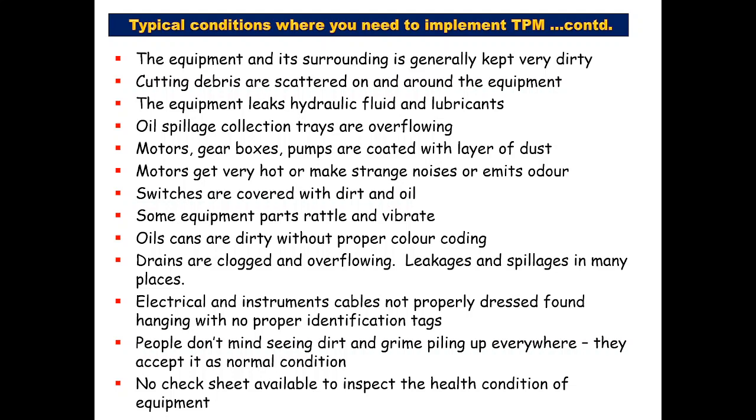This is a continuation slide of some more typical conditions where you need to implement TPM. The main point is poor housekeeping, like unwanted things scattered on the machine floor, hydraulic fluids and lubricants leaking, oil spillages, oil cans that are dirty and without any color coding, and motors, pumps, gearboxes, etc. covered with dust and grime, that is a thick layer of dust with moisture or oil. Abnormalities observed in the equipment like heat, vibration, odor, abnormal sound, no free access, electrical instrument cables not dressed properly and hanging loosely without any identification tags, and no check sheet to inspect the healthiness of the equipment.